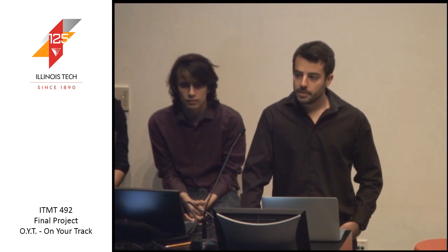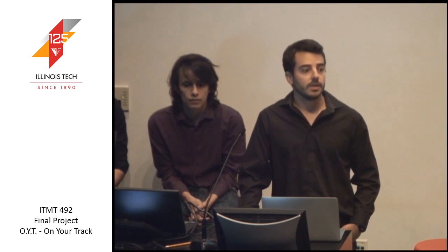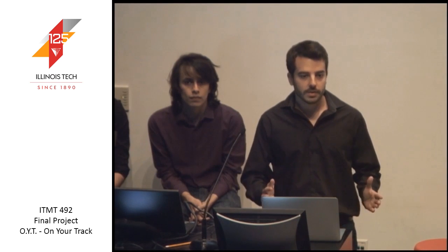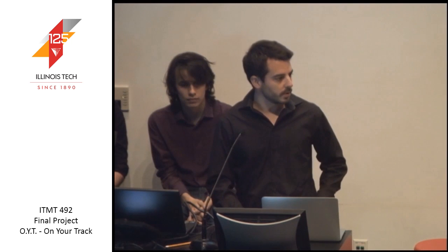In this project, we developed a PCB design, a PCB board for the project and circuit. The purpose of that was, if we built all the circuit on breadboards or boards for the prototype, as this device is moving all the time, we would have a lot of problems with bad connections and this sort of stuff. And also to show, as this is a prototype, all the components of our robot clearly. So we designed it in an understandable way, so you can just look at it and see all the sensors, the motors, and all the components of the circuit.